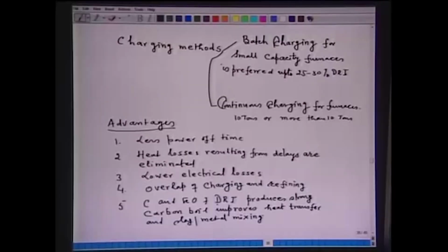So, if 40 to 50% of scrap is substituted by sponge iron, then power consumption will go up, say roughly a figure of 10%. This is mainly because you have introduced extra gangue content, and you require to remove oxygen of FeO, and because of this the power consumption also increases.